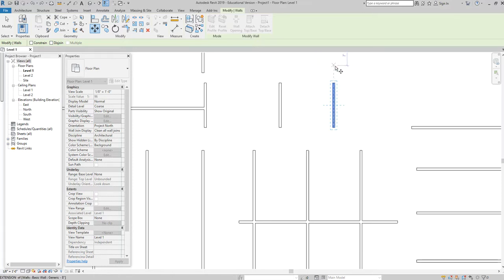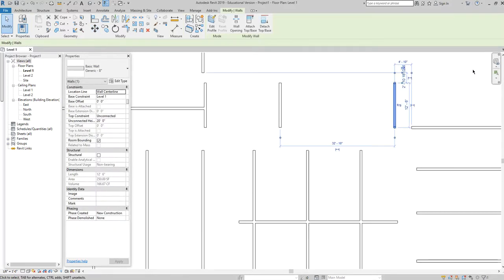The base point for me, I usually will pick in outer space. I don't pick on the object. I pick slightly above it. I select, and I'm going to say this is behind it because I'm going to move it to the right, or I select below it, all right? So I click, I move in the direction I want to go, and I get a little preview of how that object is moving, and I can just freehand it, click, and it moves, right? I don't know how far it moved, but it does tell me 32 foot 10 inches, but I was just sort of guessing, right?